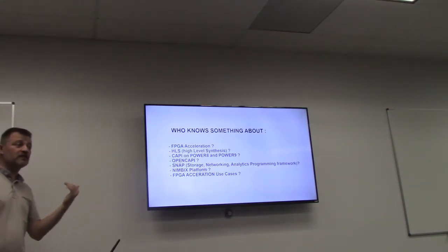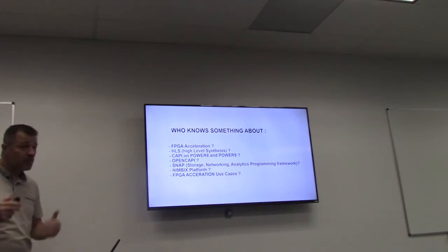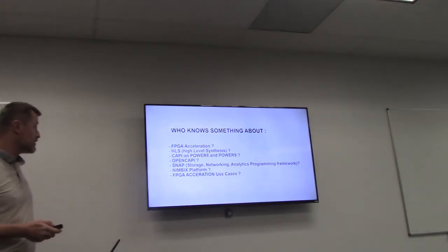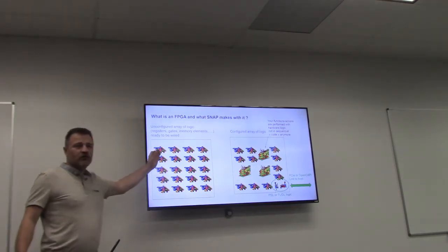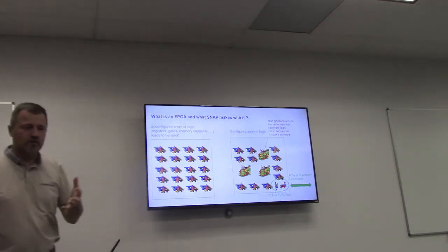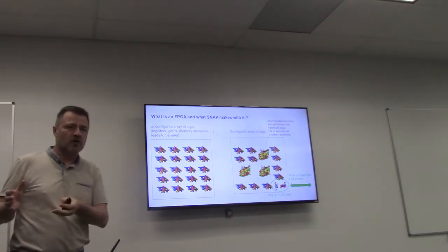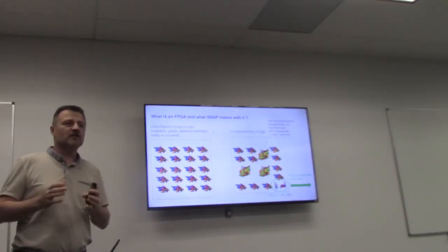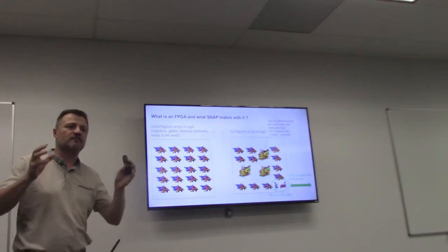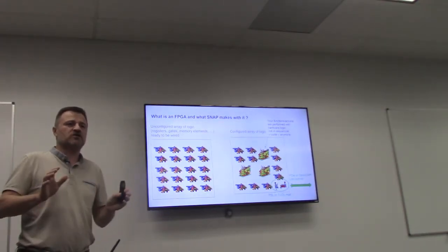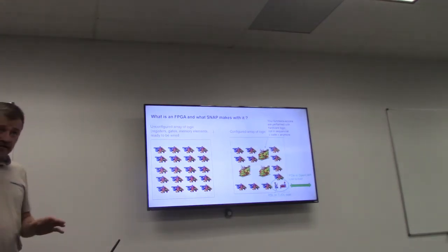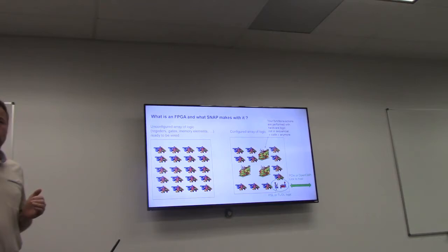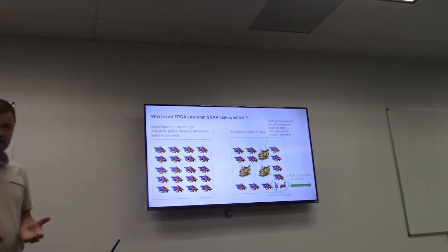Since we have different levels of knowledge, let me go very quickly over the basics and then we'll go on to the machines. So what an FPGA is: a bunch of logic. When you buy a computer, a microcontroller, a microprocessor, you get an ASIC. That means the supplier has built and hooked up everything, and you cannot change that. You buy a P8, you buy an Ethernet controller. That's generally low cost for the performance, but you get a fixed logic inside.